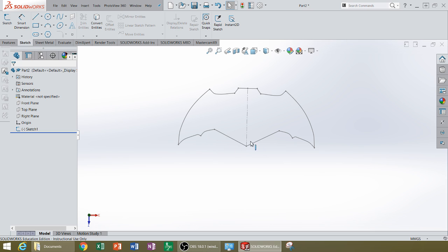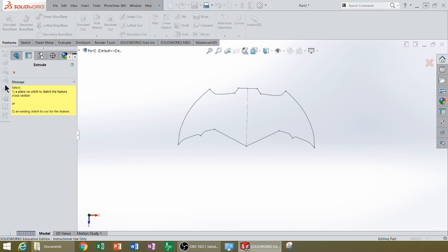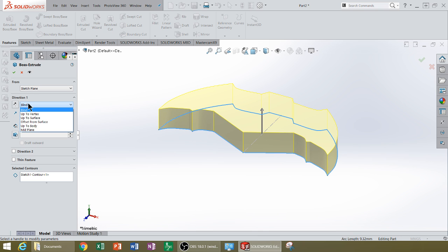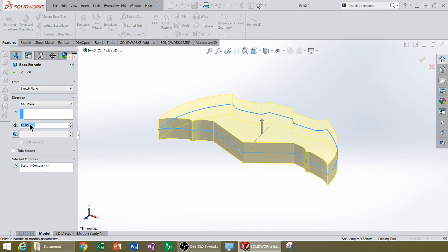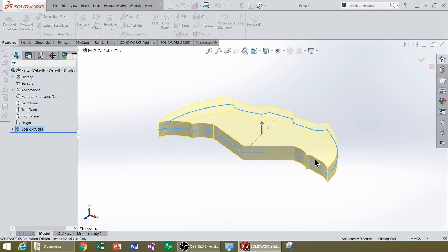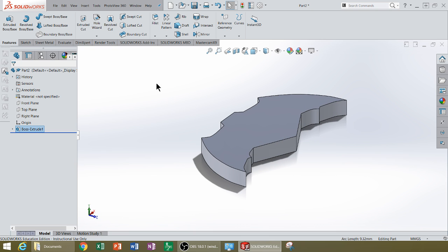explore that, but from this shape, what I can now do is extrude that, choose my body, choose a midplane extrusion. I'm going to make mine 7 millimeters, the thickness of a bearing. Accept that. And I could do other interesting things to try and make this more Batman-like.